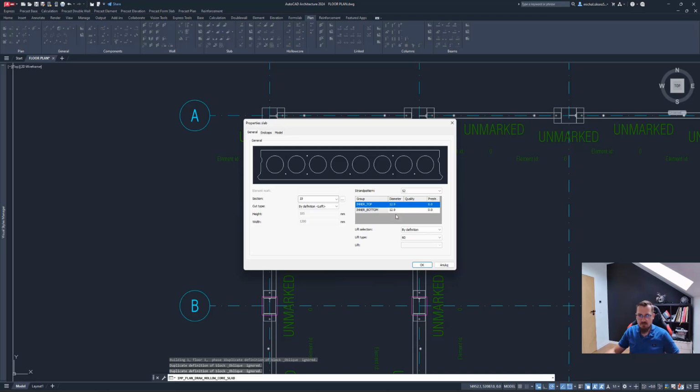There's also the specification of if you want to apply pre-stress to those, you can make sure it's in here. You can define if you want to automatically place in lifts. So that would be by user, and you would specify a lift type, but I'm going to go by definition now. So automatically my lifts will not be placed because maybe you have this special crane with a hook that will attach to the sides of that. So that's good, but I'll show you in a second how to add those lifts if we need them for whatever reason, or if we need them by design in our factory, then I'll show you how to add them at a later stage, or you can add them now.